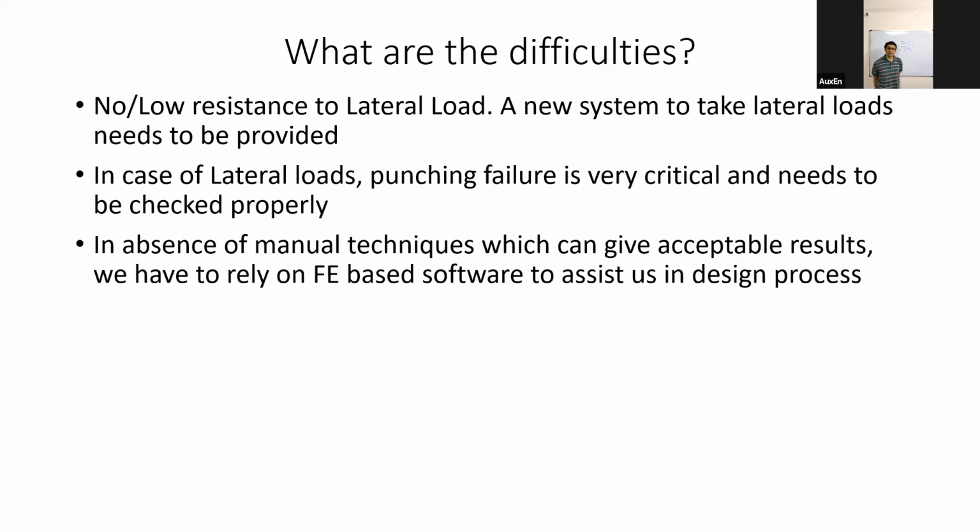Those are resting on your columns. And when lateral load comes, the load path that was getting generated between a beam column system is not generated over here so effectively. So you are not able to effectively generate a good load path to transfer your lateral loads.